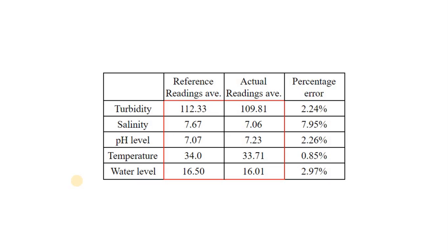The salinity parameter had the largest error at 7.95. One contribution to the discrepancy in salinity readings is its correlation with room temperature. When water temperature is hotter, water molecules will slightly expand, causing salinity levels to drop. Inversely, when the water temperature is cooler, salinity levels will slightly increase. The duration of the test where salinity levels were acquired lasted approximately 8 hours, during which room temperature where the sample was stored varied throughout the day, causing irregularities. The remaining sensors met the researchers' expected error of less than 5%.